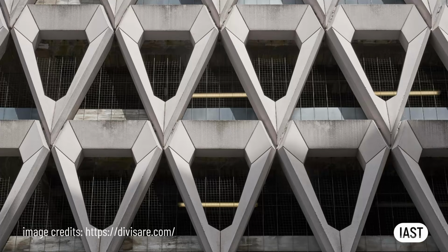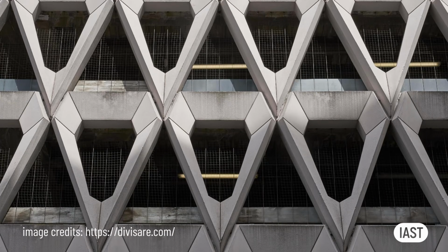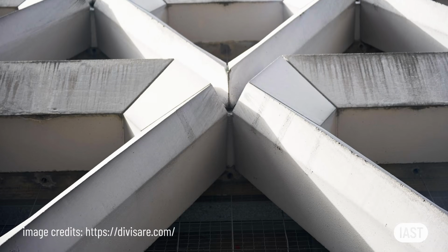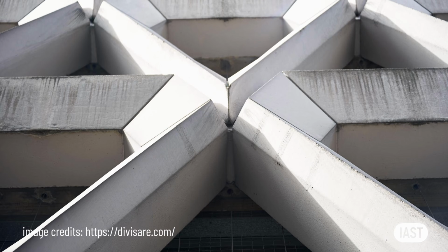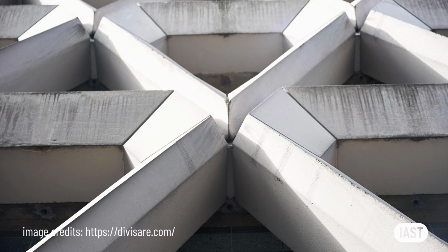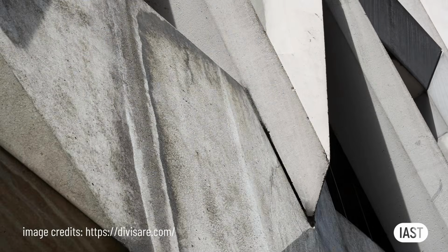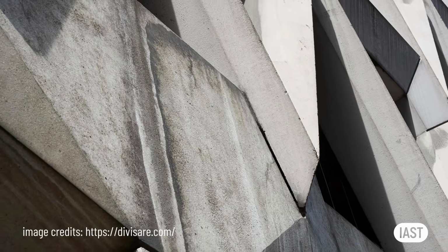Welbeck Street Car Park's concrete screen has been exposed to the external environment for the last 50 years, and all surfaces and connections are available for inspection. Judging from the photographs we took and those available online, the existing structure appears to be in a very good condition, with only minor stains on the surface. There are no visible cracks or rust stains anywhere.